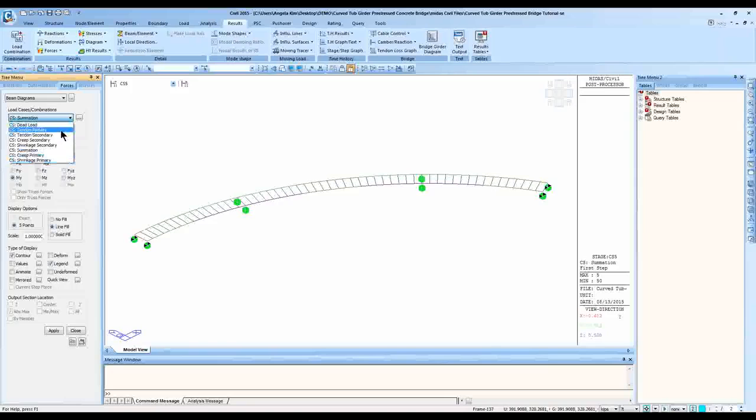So the tendon loading, the program can obviously know which one's the tendon data. Creep is calculated based on the material and the surrounding component, not exactly the loading. The program knows and extracts creep and shrinkage, secondary, primary results in different categories. So this is something that the program does automatically for the construction stage.